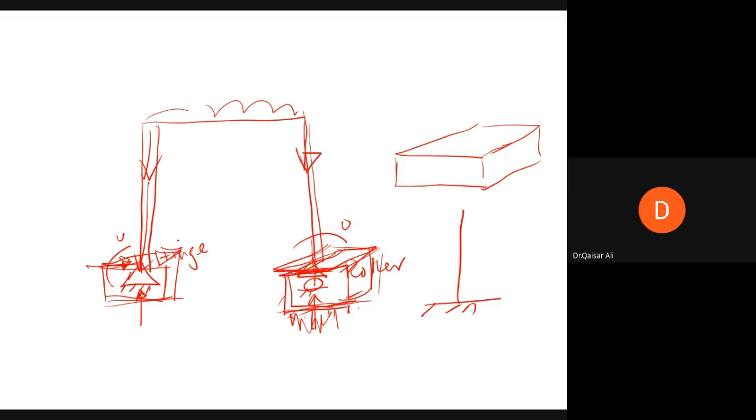And how do we know whether this will offer bending moment resistance or not? For this we will have to design this support. So how can we do this? For example, in the beginning of your analysis, you assume that it is a fixed support, okay? Because at the beginning you do not know what kind of footing you will provide. Let's say you are assuming in the beginning that this is a fixed support. I will provide a fixed support.